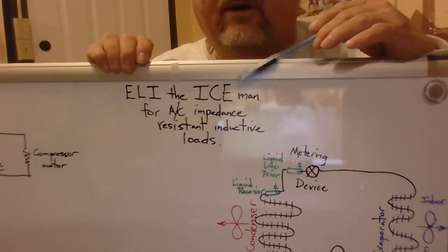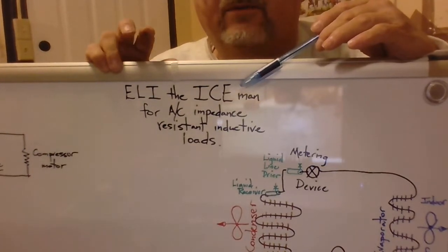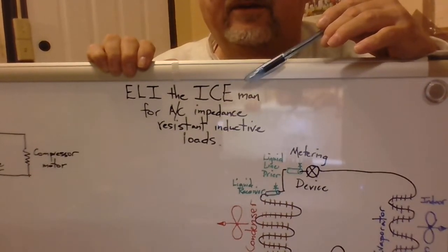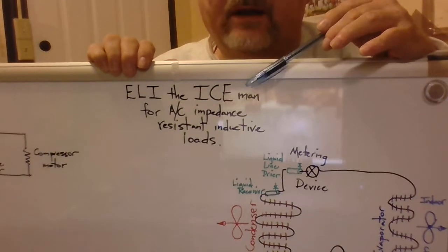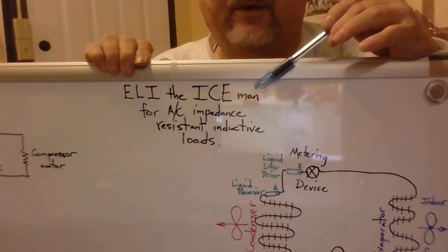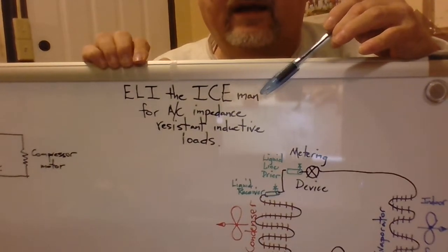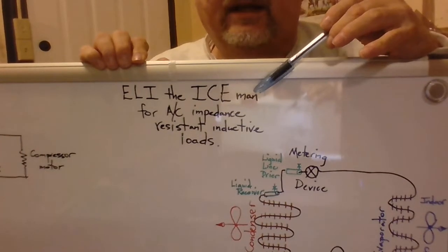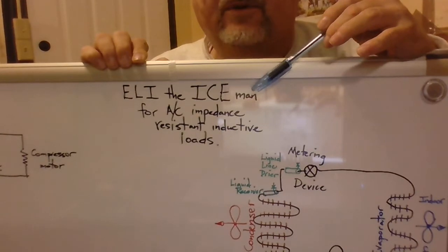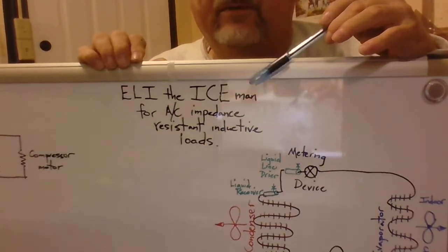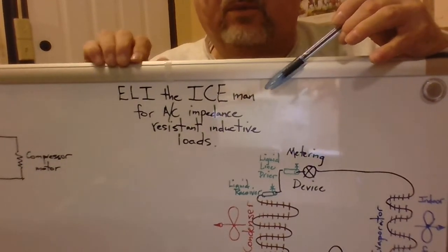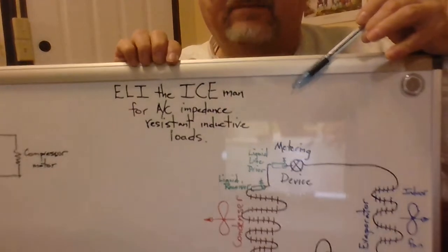If you have 3-phase power like on a commercial setup, two legs will read very high and one will read very low, and eventually that will lead to failure of something to do with the compressor or a condenser fan motor, which will fail the compressor at some point. So you want to address those problems early on, and that's why understanding these concepts enables you to understand the importance of always being attentive to the PMs that you do on rooftops, package units or split systems, because the small things will become big things later on if not addressed properly.